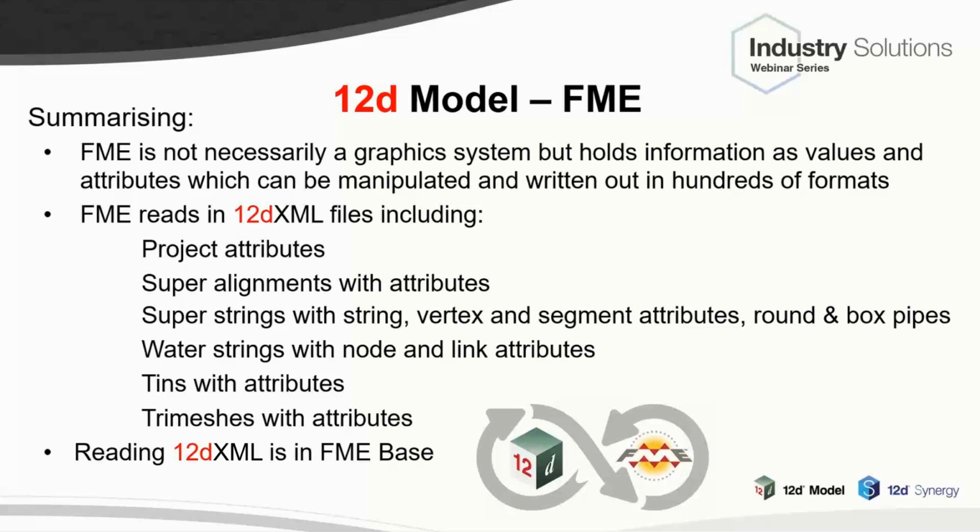So basically with FME, it does then mean that virtually any of your clients, you can hopefully just give them 12D XML data, which is your data exactly, so you don't have to fiddle with it. Or if there's something they can think about later, oh, I wish I had that bit of that attribute, it's all there in that 12D XML file. So you are providing them then with basically your one source of truth. This is exactly the data you've picked up, exactly the data you've designed, exactly the data you've manipulated. Whatever you've done with your data, you are giving it to them as your data, and then they can make their decisions on how they want to then manipulate it.